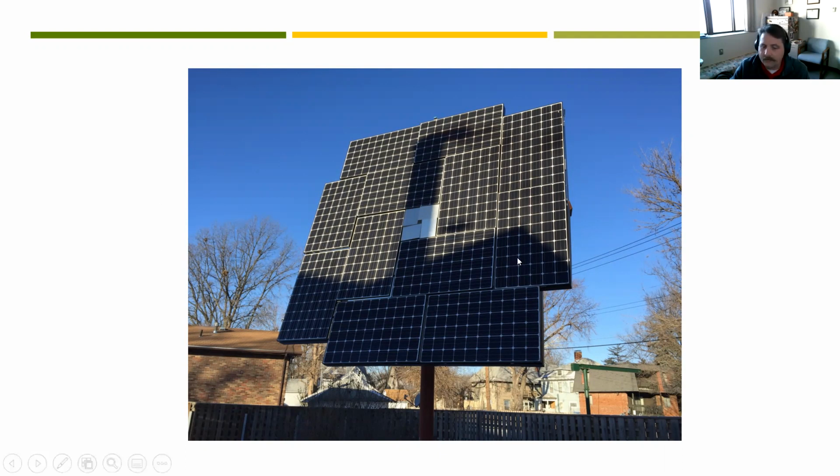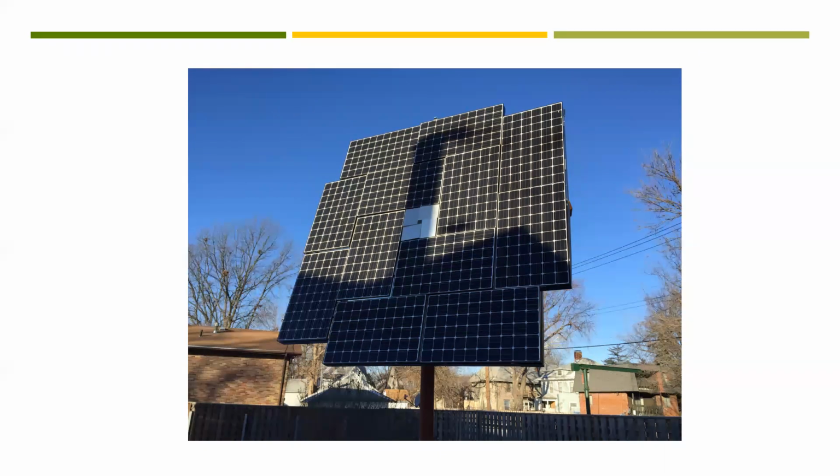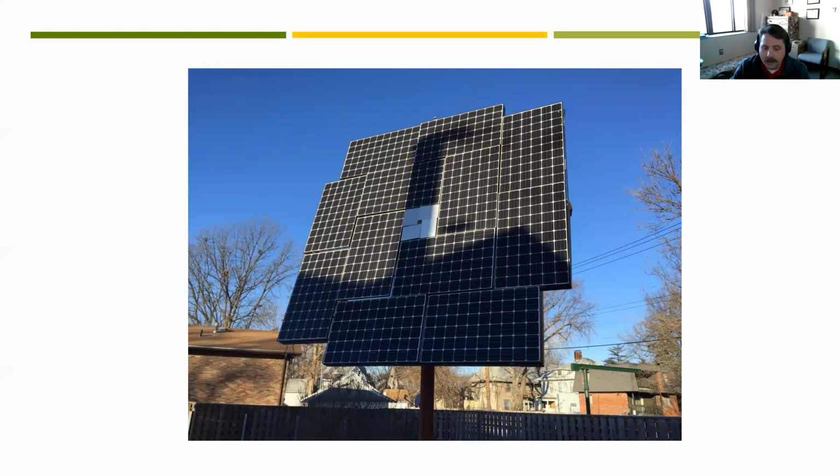The panels that have shading are producing substantially less, maybe not completely off, but substantially less than ones that don't have shade. Essentially, there are only about three of these solar panels that are probably putting out the most they could, in enough full sun to generate all that they can at that moment, and the rest of them have some reduced capacity due to the shade.